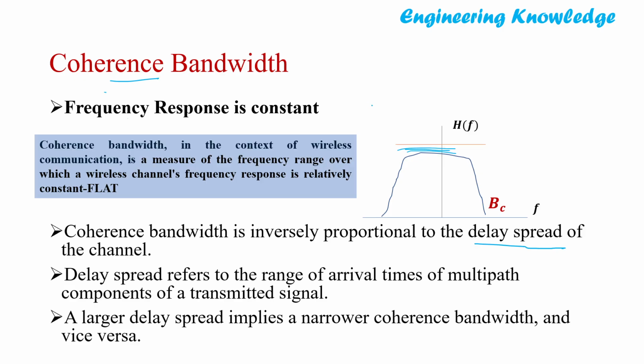So in a very rich environment, a scattering-rich environment where there are multiple multipath components traveling, the delays of the first component tau_0 and the last tau_(N-1) will be very large. This will yield a very large RMS value and therefore a very small coherence bandwidth.